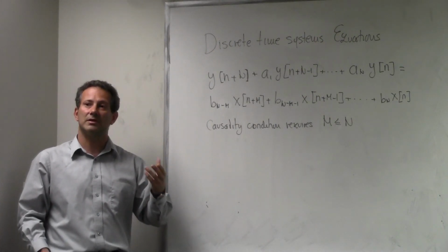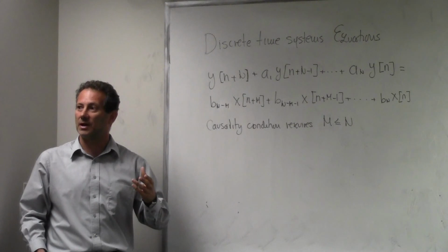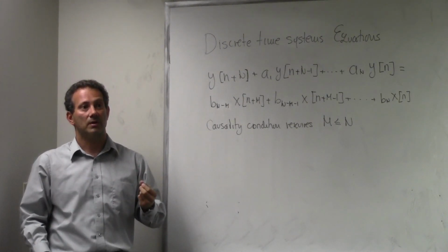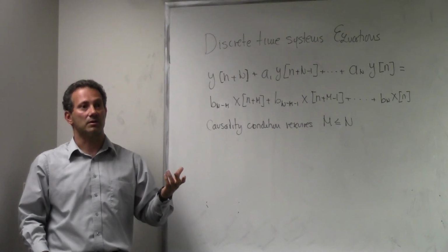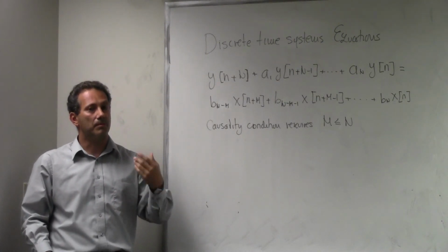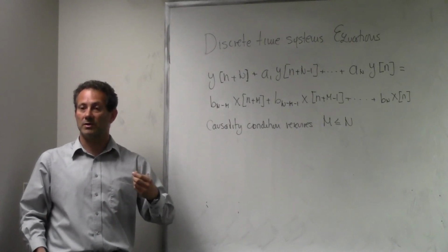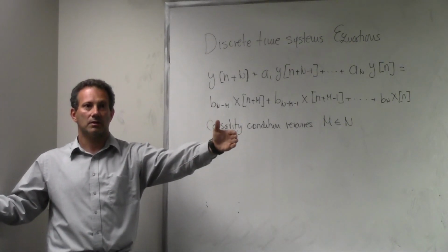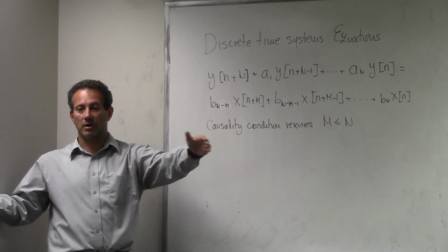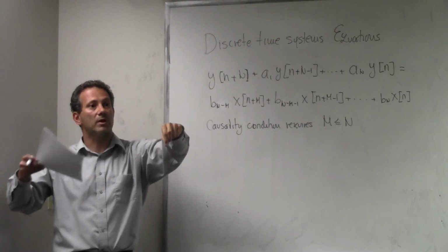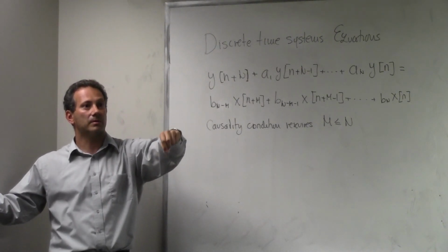Causal is not something that is exotic. A lot of systems are causal. Everything that we process that's non-real time can be non-causal. For example, the best noise reduction algorithms are the ones which take the entire sample and then work to reduce the noise. For example, at the first sample, by knowing where this entire signal ends up.